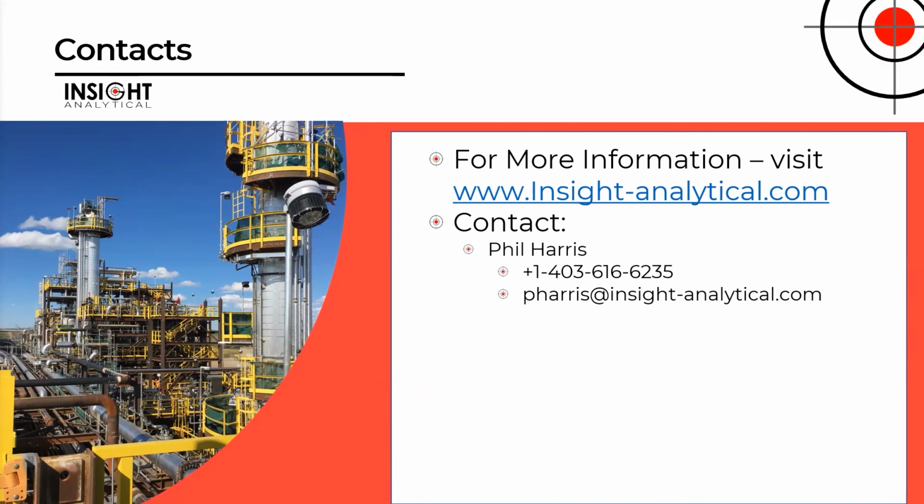Okay. So when it comes to communication capabilities, what can it give us? For example, Ethernet. Yeah, Modbus over TCP/IP is our standard. We also have a cellular connection to each analyzer. We provide software so you can have a remote way of logging into the analyzer and see how it's running. So if you're here in Calgary, but you want to know how the plant in Grande Prairie is running, you can just log into the analyzer and see what the results are.